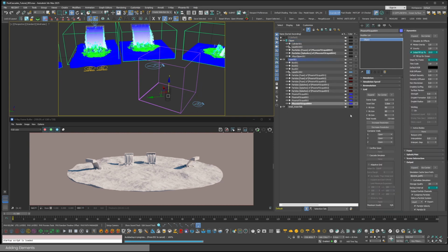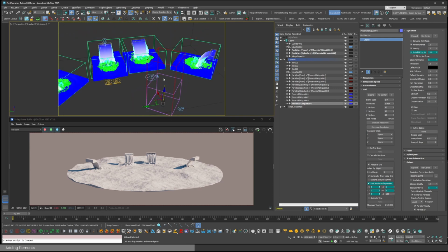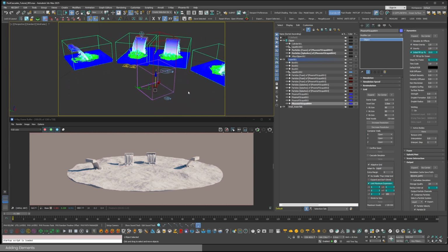And here inside the grid rollout, I can enable the adaptive grid. It will adapt to the liquid particles. And I can limit the expansion on the -z axis. And you know what? Let's limit all of them. Set them to 0. It is actually not a great idea to have an adaptive grid that expands horizontally when using the ocean fill. I'll leave only the +z axis at its default 100 voxels. That's how many voxels the container will be allowed to expand. Let me start the sim.